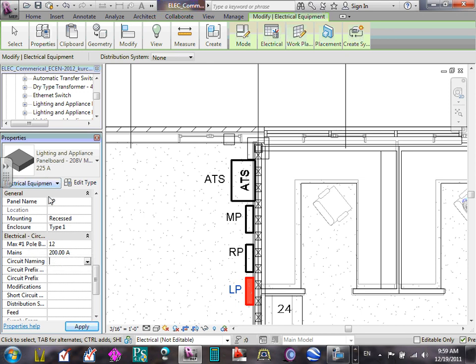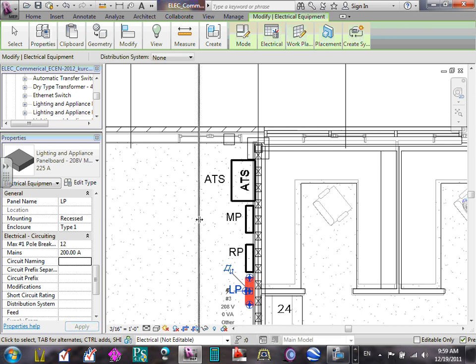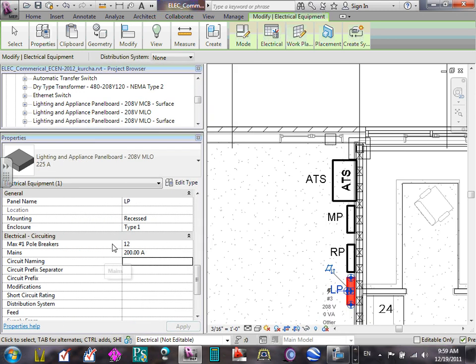Can you guys go to the function that says circuit? I don't know if you can see it here. You can expand this, by the way. Go all the way to electrical circuit. Now, right above it, if you know how many problems we had last year with this, Rob? Right above it, how many circuits you can feed from this panel? Can you guys see that? Does yours say 12? Well, that's a disaster. Here's what happens when you start circuiting with this panel. The students used to come and say, Chad, it's not circuiting anymore. It ran out of room.